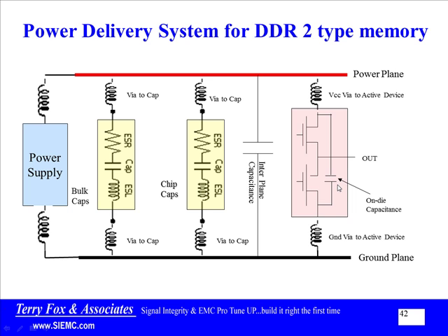Now, one clever thing that Xilinx did, and I'm sure Altera's got an equivalent, is they actually put, I think it was 47 microfarad Murata chip capacitors inside the ball grid array. Now that's pretty slick, because what they're doing is getting that capacitance on the chip side or the die side of this mounting inductance, and that is a wonderful thing to do.